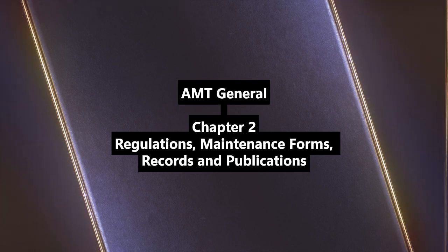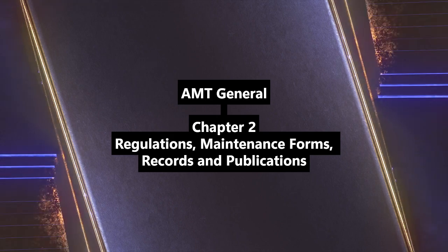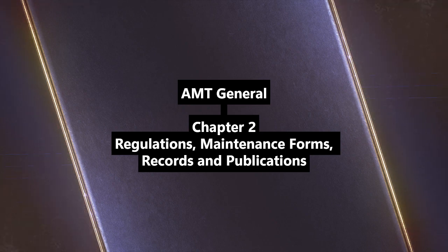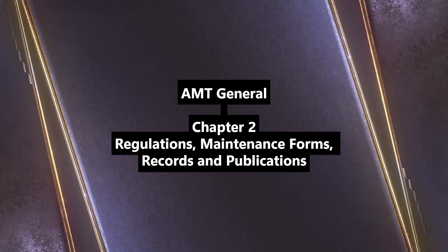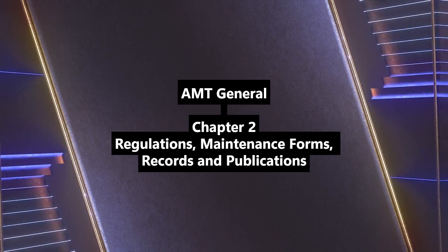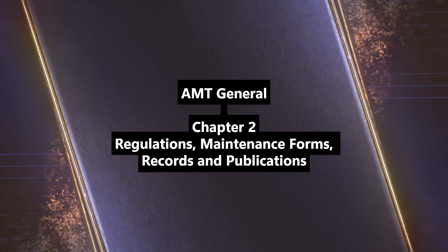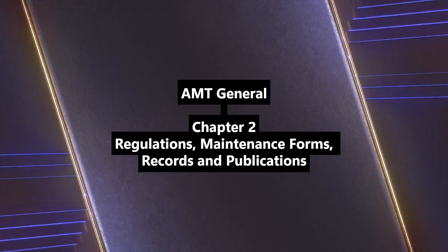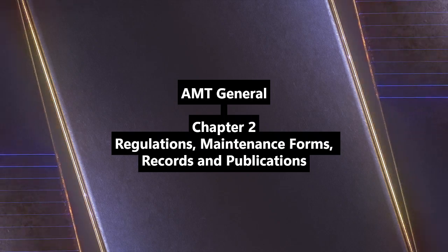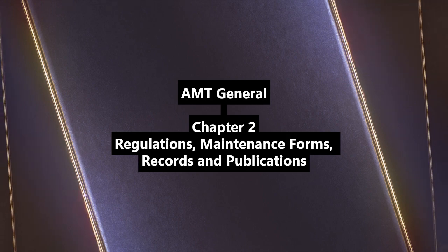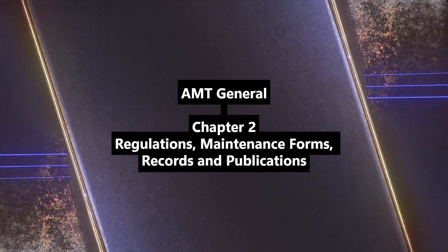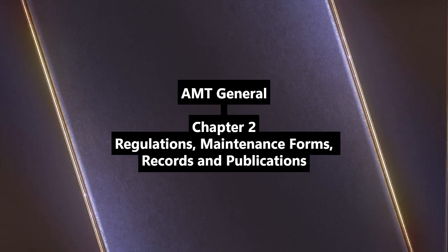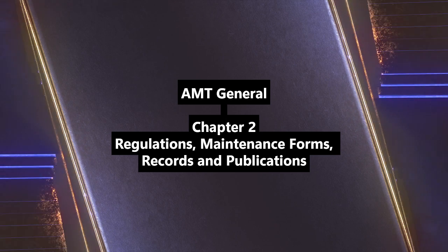Okay. What about Part 125? 14 CFR Part 125 is for certification and operations: airplanes having a seating capacity of 20 or more passengers or a maximum payload capacity of 6,000 pounds or more, but used in private or non-common carriage. So large aircraft, but not operating like a public airline. Yeah. Corporate flight departments, maybe? That kind of thing, yes. They need operations specifications, or op specs, covering authorized operations, manuals, inspection programs, weight and balance, etc. Subpart E deals with their special airworthiness requirements.